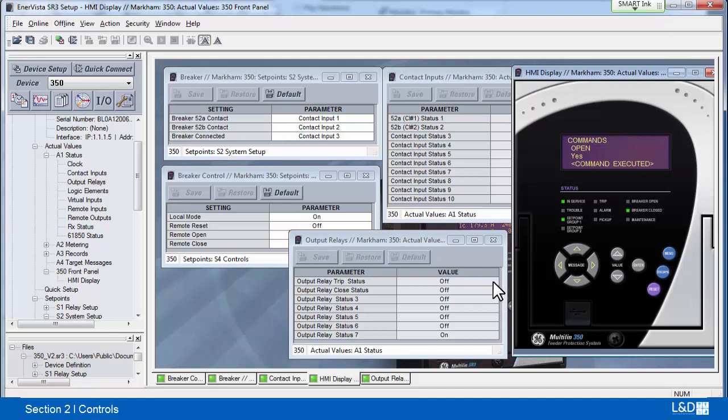And now we see this status turned on momentarily, so that means a trip command is sent out from the output relay. Now to simulate a breaker is open, we use the RTT switch to simulate the breaker status is open. Next command we can try is the breaker close. So go to the close, press enter, change the command from no to yes, and press enter key.